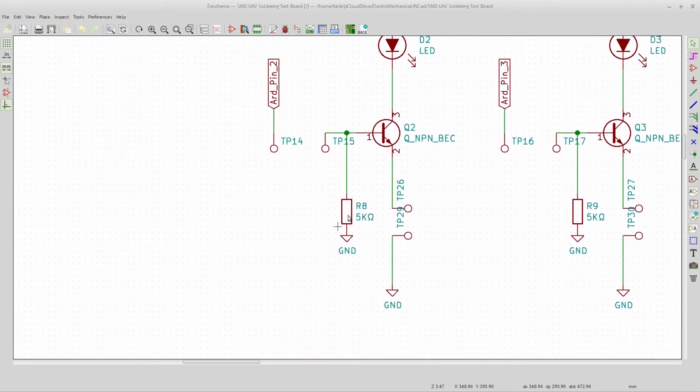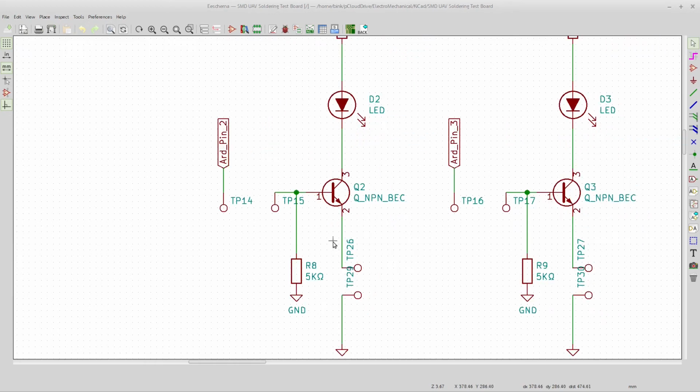This one over here is allowing the electricity, the current, the power. I'm trying to, again, keep things kind of vague. It's trying to give it a place to go to ground. It's trying to take this circuit here and pull it down to ground. Maybe slowly, maybe quickly, depending upon, again, how you size this, okay? So this one right here is called a pull-down resistor.